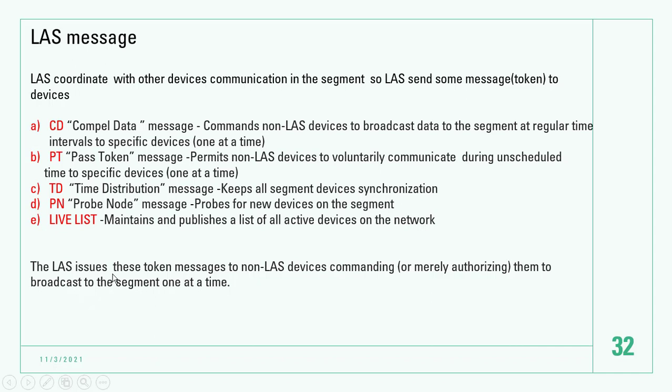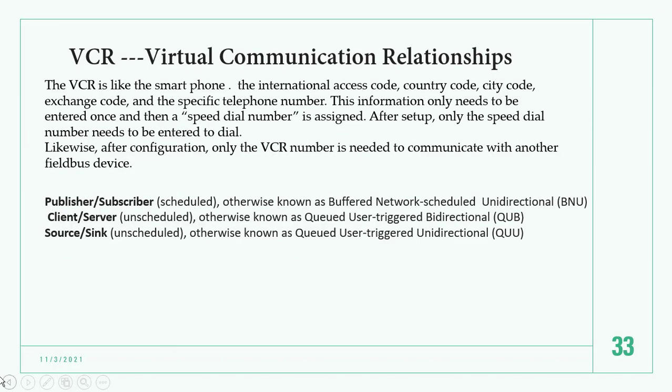The LAS issues this token message to the non-LAS device, commanding it to broadcast to the segment at the time. The LAS just sends this message, and the other devices just respond to this message. Okay. Now we talk about the VCR.